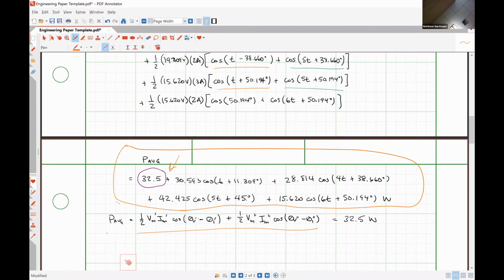And 9 times out of 10, we're going to be significantly more concerned with the average power than the instantaneous power anyway. When we design circuits in the real world, we look at the maximum values of voltage and current, usually current, to get a sense of what size of breaker we might need to prevent damage. But as far as the actual operation of the circuit, everything is based off its average value.